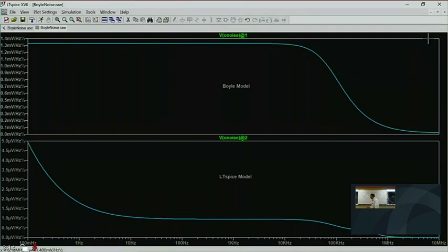getting, a microvolt. This 1/f performance here, that is the 1/f noise of an LT1028. Its corner frequency is here at 3 hertz. That is the noise you get. Now, what about all this structure up here at high frequencies? What about here? At real high frequencies, you don't see any noise. And there's certainly noise out of an LT1028 at 10 megahertz.